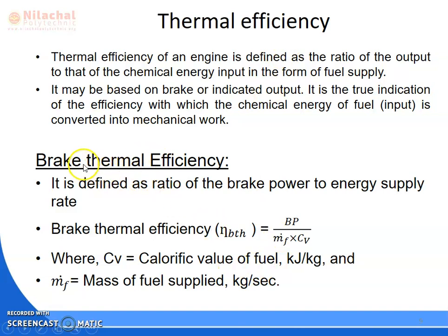So first we will discuss brake thermal efficiency. What is brake thermal efficiency? As I told you, efficiency is output by input, but in the case of an IC engine, output is power. So we are calculating brake thermal efficiency. So your output is your brake power, and what is your input? Input is your fuel supply.